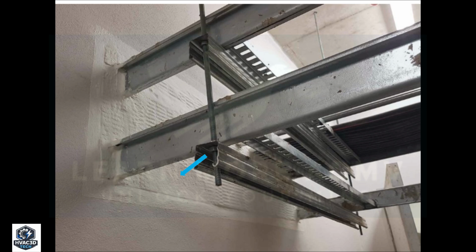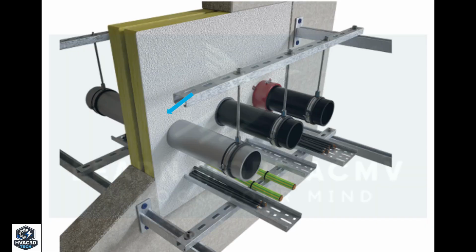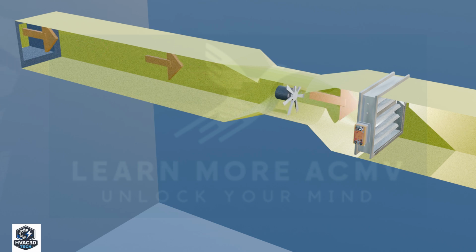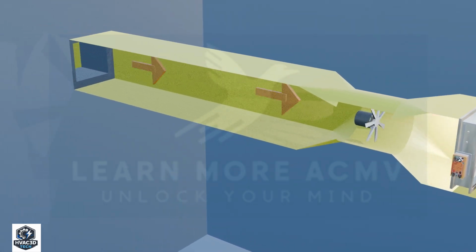Pipes and cable trays can be sealed with fire sealant and rock wool, but ducts cannot be fully sealed because air must pass through them. This is why fire dampers are used.